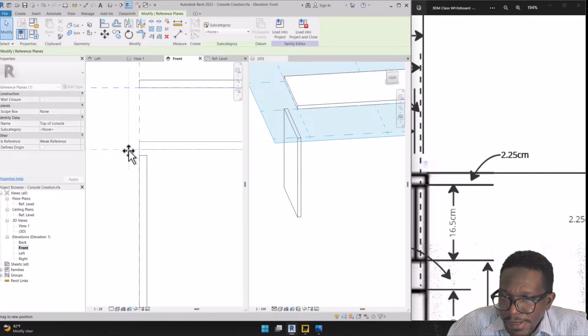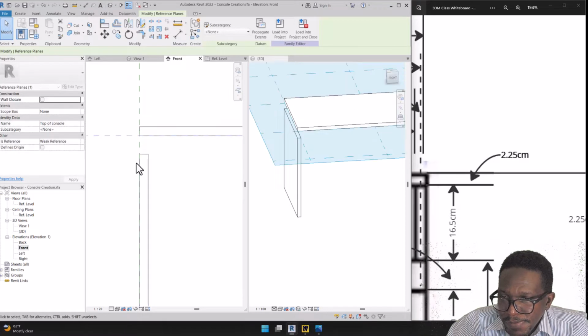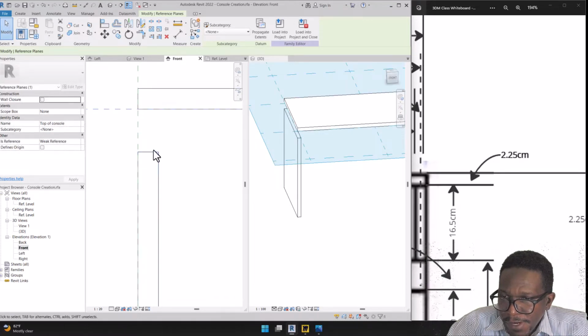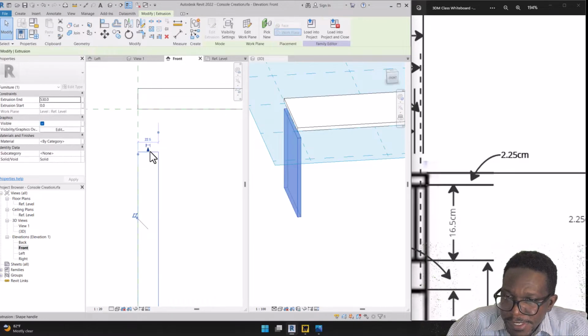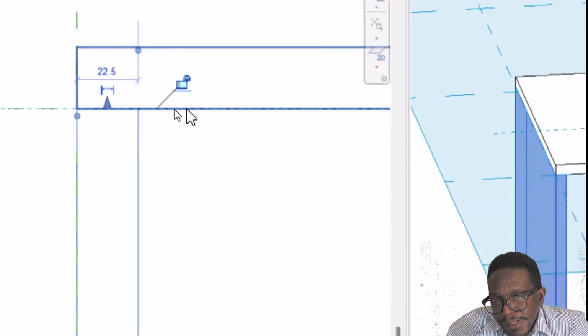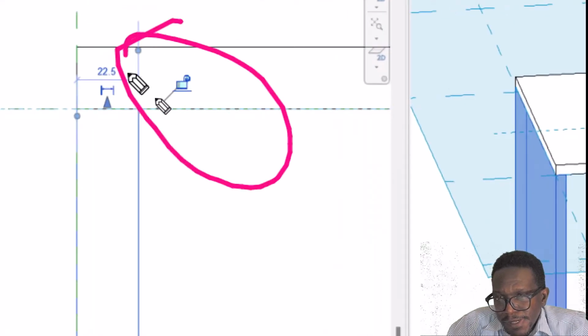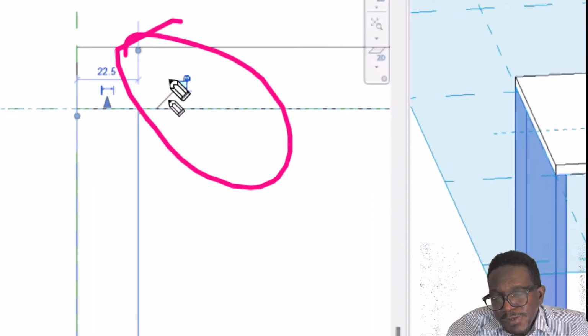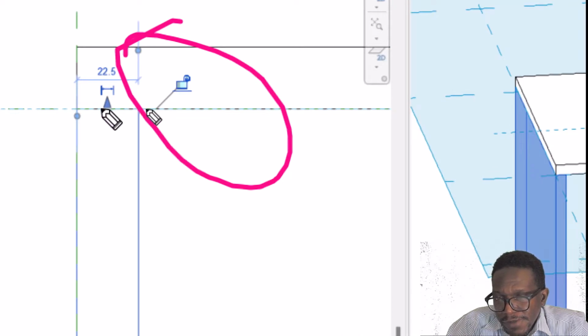And let's make one edit here. Notice that if I click this and I extend this up, and I'm gonna hover so that it snaps on this work plane, and I release, notice I get a little lock here, and this part here is important because once I lock this is telling me that, hey, this surface is going to be locked to this work plane.